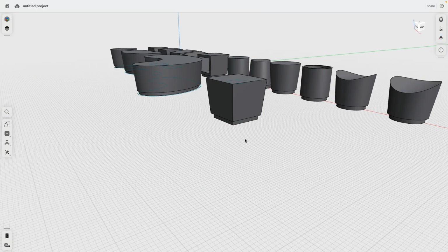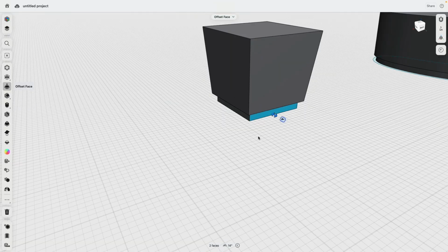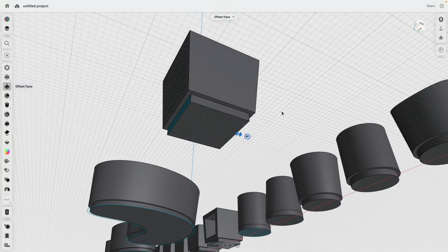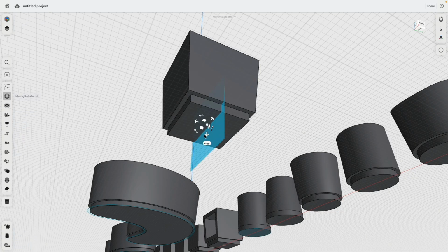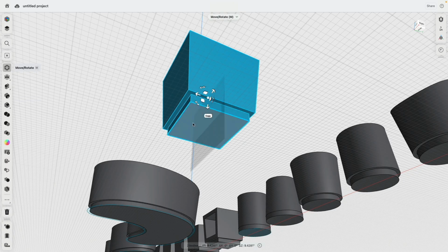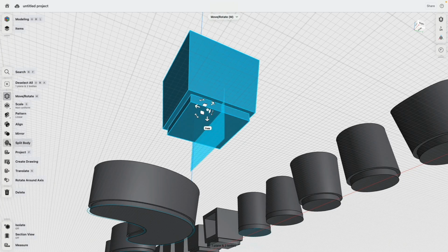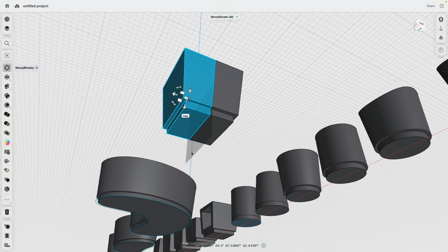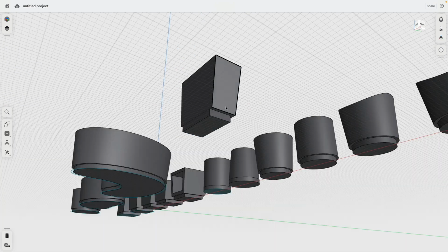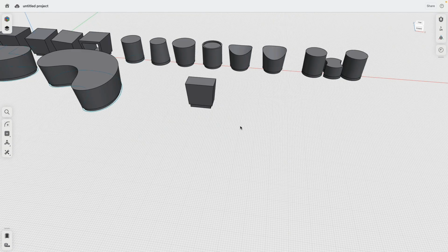I would like this to be sliced through the center. And because I do have here two parallel faces, I can say, create me a plane at the midpoint. There's the plane, and this plane I can use as a split tool. Then you and you, and I think the plane at this point we can delete. And there we are. There is that piece.